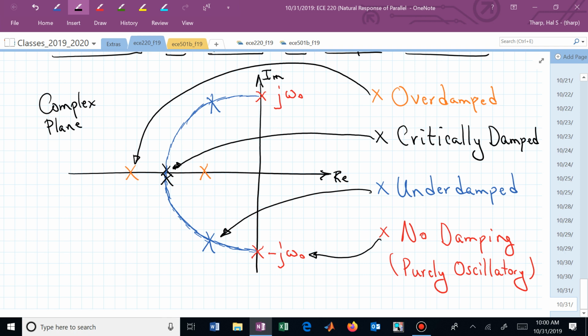The way to think of this, maybe, you come up with your own way to visualize this, but let's say we're in the tank circuit. We're on the imaginary axis. We now start to increase damping, introduce the R. If we kept omega naught the same, do you see that we would stay the same distance away from the origin? Omega naught is our resonant frequency, or the natural frequency, and now if we increase our damping, we're actually swinging around and having less vertical distance.